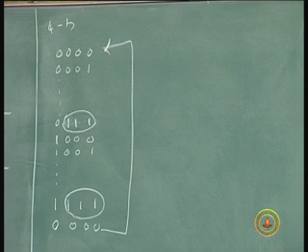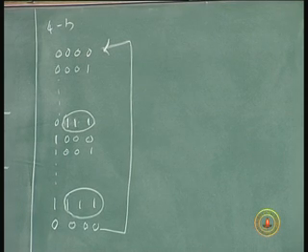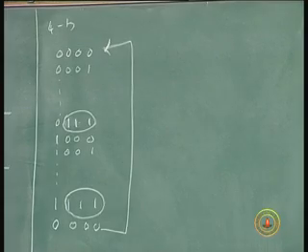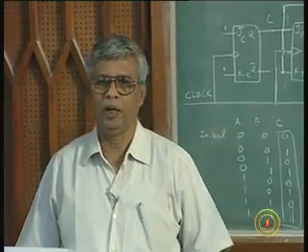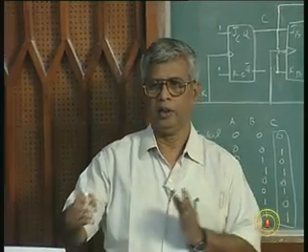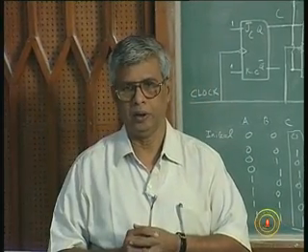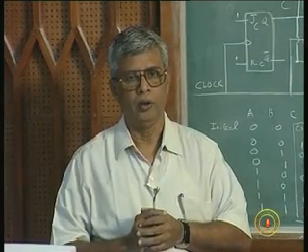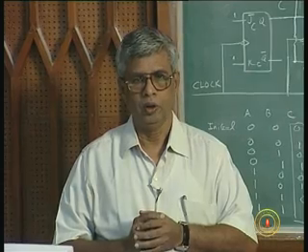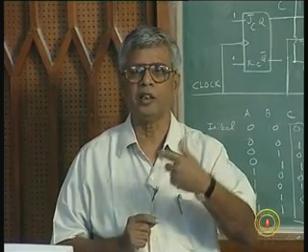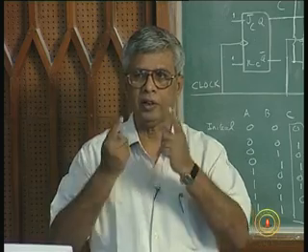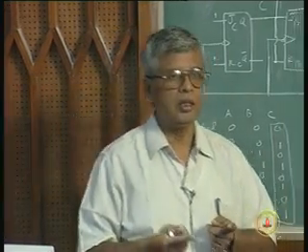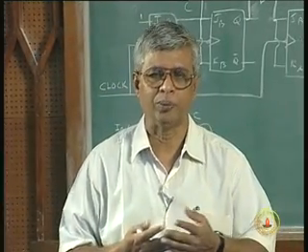So, I will repeat. When all the previous flip flops have changed into 1, you want the toggling of the next flip flop, and that has remained for several clock cycles before the next change can happen. This is the concept of a synchronous counter, wherein the clock is given to all the flip flops, and the change in the Q is controlled by the outputs of the flip flops.